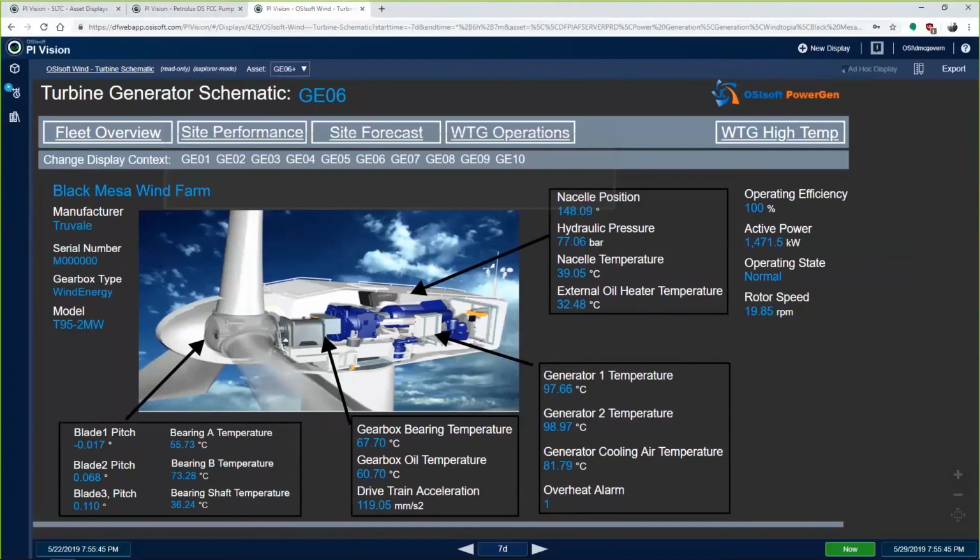Is the PI system more of a data acquisition system and not a SCADA system, or system control and data acquisition? One viewer noticed that there were no parameters changed in the process of your demo. Yes, that is one thing that is very crucial to recognize: the PI system is not a control system. We never really want to be making any changes on your equipment.